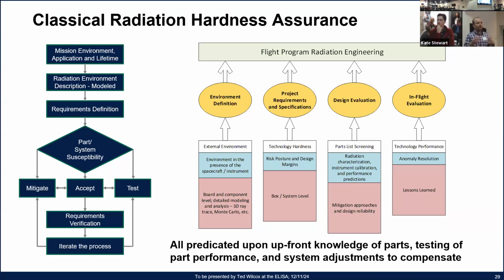What that means is not just tolerating an effect in the sense that you've filtered out a voltage glitch or something. It means having a distributed architecture where you have memories being stored in multiple locations. None of the EDAC is in one place, and you don't have all the primary memory in another. You're able to operate through failures of individual devices. Those are some of the more resilient designs that we've seen at a system architecture level, like, use the Roman solid state recorder as an example.